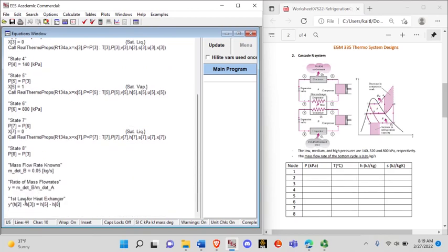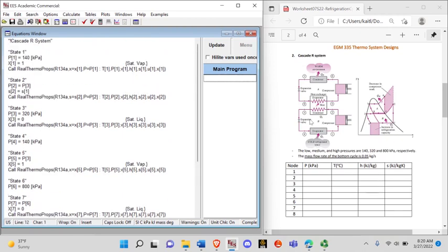So now we're one step closer because now we know H2. The only unknown we have for this is H8 and m dot a. But with these three equations, we could find both. So now that's good. But we're just going to continue with these constant entropies. So we're going to find more. And we also see at state 5 and state 6 is constant entropy. You can also write a comment for the reason, and that's because of the isentropic compressor assumption.